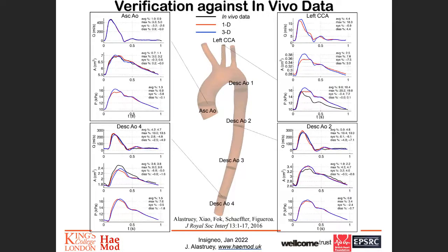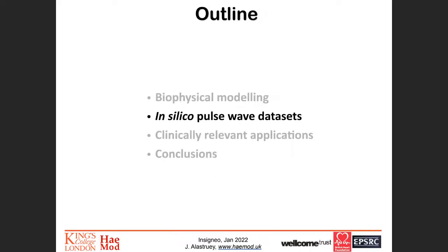And so then we were able to compare again 1D versus 3D, flow on the left and pressure on the right with time. And yeah, we got average relative root mean square errors smaller than 3% in both pressure and flow rate along this idealized model of the full aorta. And then the next thing that we did is also to test the accuracy of the 1D